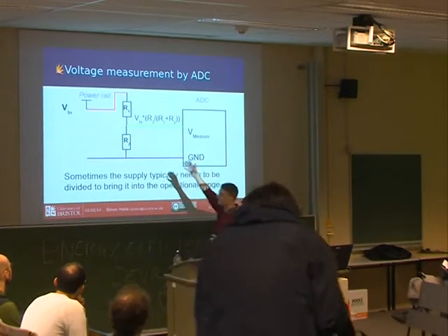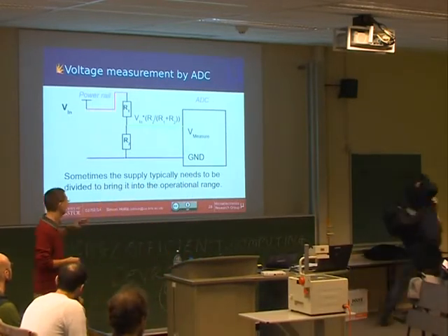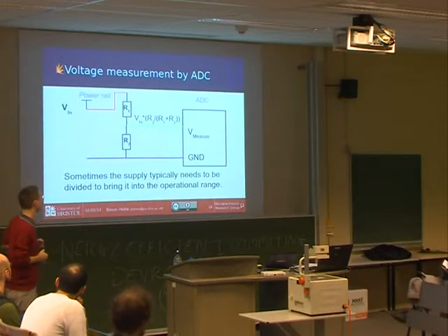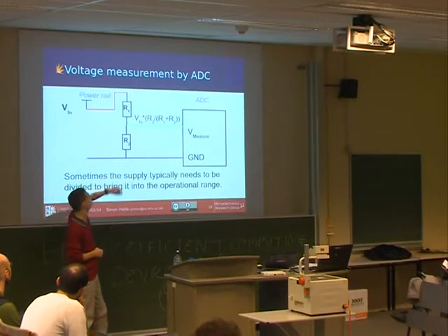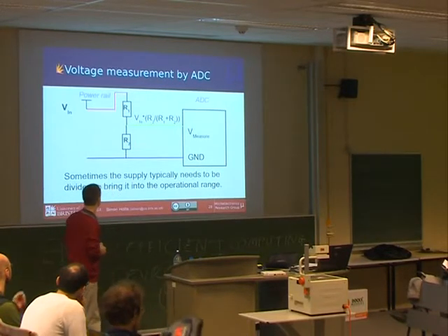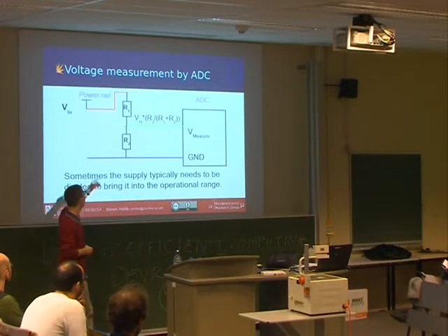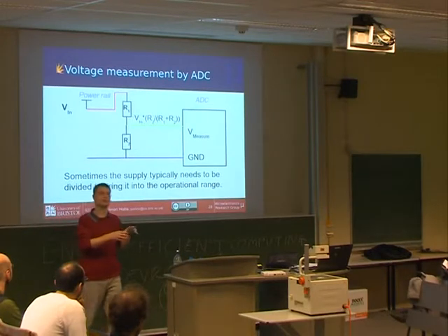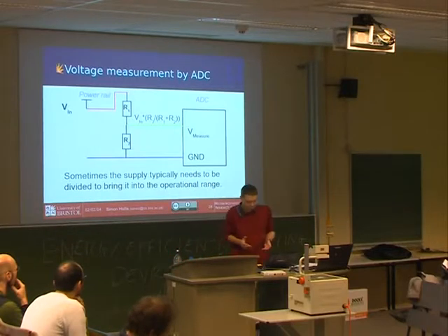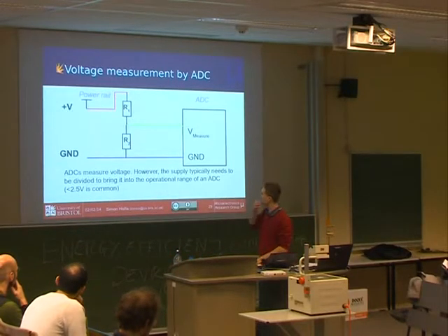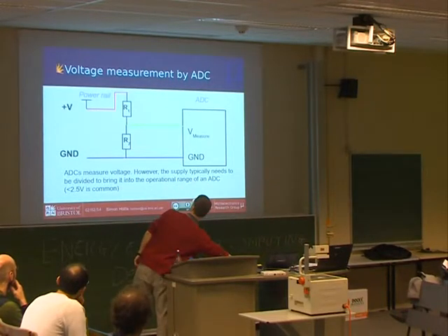The first thing we want to do, we build this structure called a potential divider. It uses 2 resistors, and that allows us to drop a high range of voltages into a smaller range. And it's determined by the equation that's up there, and V out is the voltage in times its ratio of resistors. So if we want to halve the voltage range, so we have 0 to 5 volts, we put two identical resistors in there, we'll get 0 to 2.5 volts out. And then we bring in this range of the ADC. So that's nice and easy. And we'll do that when we need to.